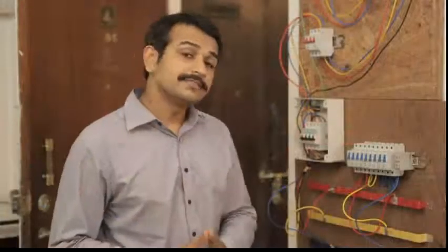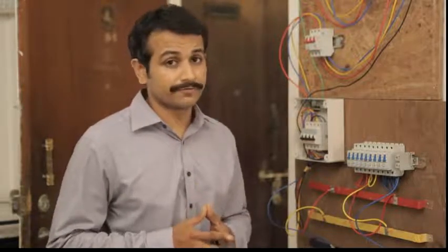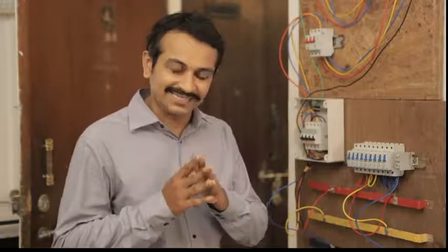So, friends, this completes our designing and wiring of distribution board with the input main supply. Earthing wire from MCB, phase wire from the MCB switches and the neutral wire from the output of wire connector will be further connected to the switch boards of their respective rooms. This part we will see in the next session.